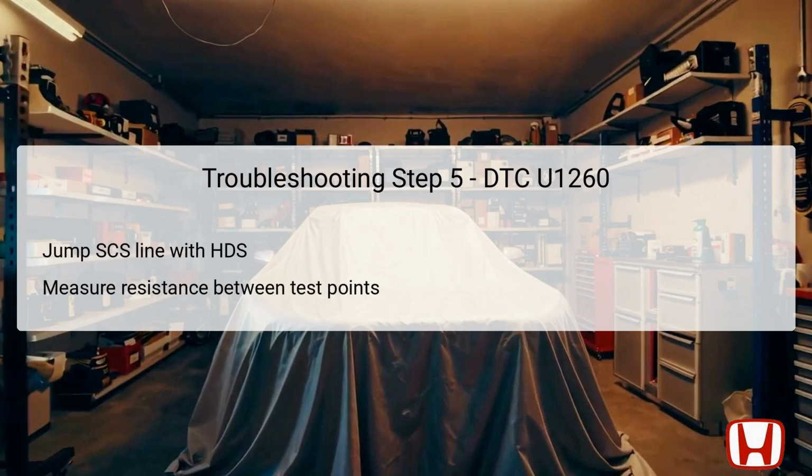Step 5 emphasizes the importance of checking for an open wire in the EOP-SIG, electronic oil pump signal, line. The technician must first turn the vehicle to the off mode and jump the SCS, service check button, line with the HDS. This will help safeguard the TCM from potential damage during tests. Post-jumping the line, the auxiliary transmission fluid pump 4P and TCM connectors should be disconnected.